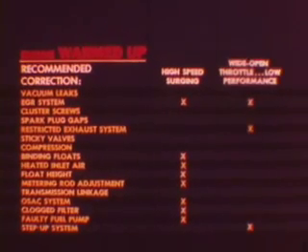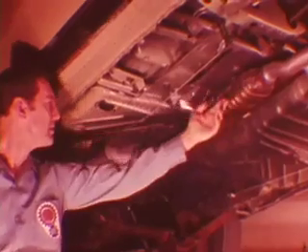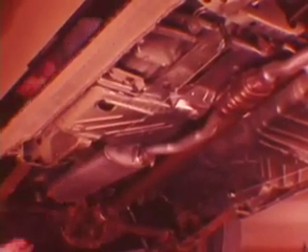As with heavy throttle hesitation, low performance at wide open throttle can also be a fuel supply problem, so check the fuel pump output and filter condition. Also, check for ignition system problems. Last of all, don't overlook the possibility that the exhaust system might be restricted, causing back pressure buildup.